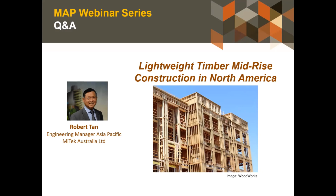But yeah, there are a lot of dedicated systems, and we have also seen some hybrid steel frames, mainly for retrofitting some buildings to provide seismic resistance in the lower story. But generally, the plywood and everything is quite capable of dealing with all the seismic action with those tie-down rods that we've seen. I think timber performs very well in seismic applications because there are so many connections that it makes it quite a ductile type solution.